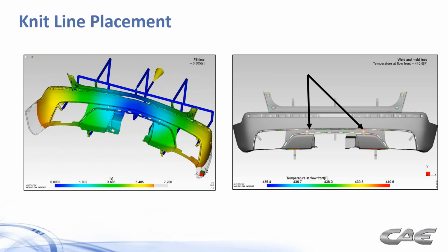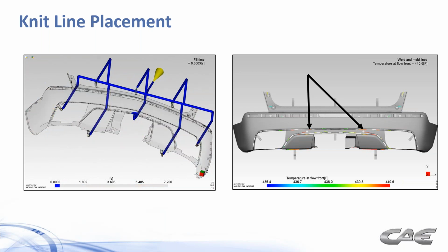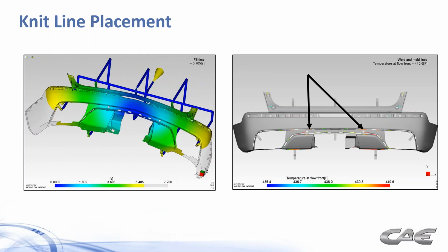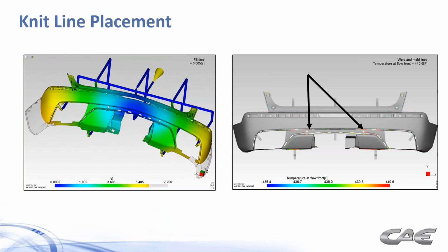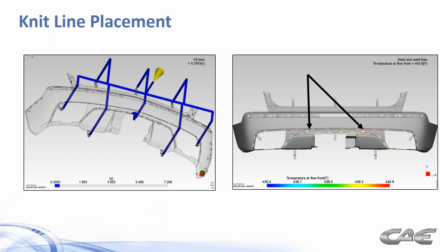Okay. And for example, in terms of pressure, let's say, is it like a safety factor that we should apply to be within the safe range? Yeah, so I mentioned earlier, there are a lot of things that aren't necessarily directly accounted for in a mold flow model. Leaky check valves, I can't account for that. Oftentimes we have the injection nozzle itself on the machine that we don't know the geometry of. There's a pressure drop associated with that. It's not unheard of to see upwards of 5,000 psi pressure drop through the injection molding machine nozzle. More typical numbers would be in the 1,000 to 3,000 range.